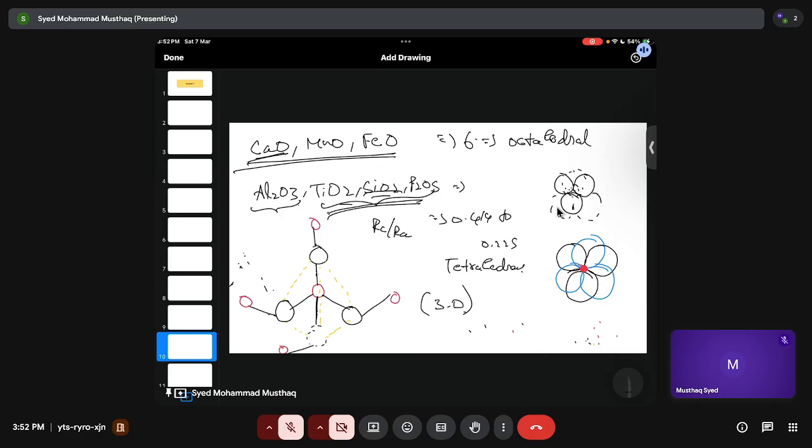Now what does this calcium oxide do? It will give away its oxygen atom, right? So you will have your oxygen, and this oxygen will be given to one of the silicon atoms, because when you try to break this, one silicon atom will get oxygen, the other will not. So the free oxygen will get associated with that extra silicon atom, which we have cut right now, which is deficient.